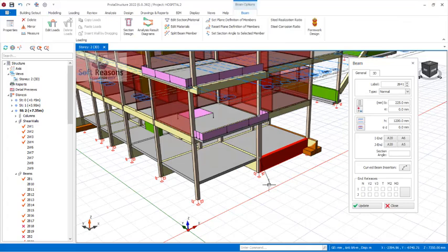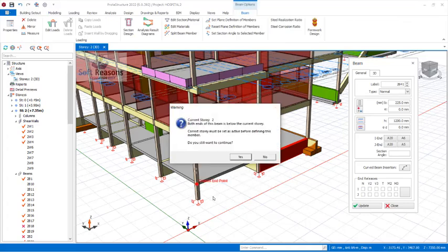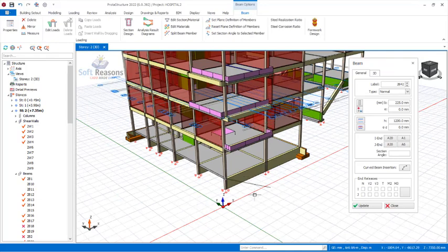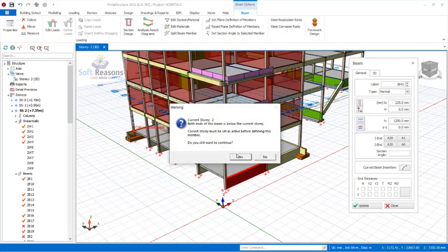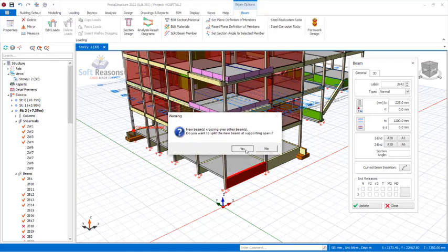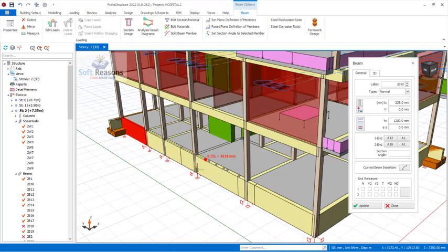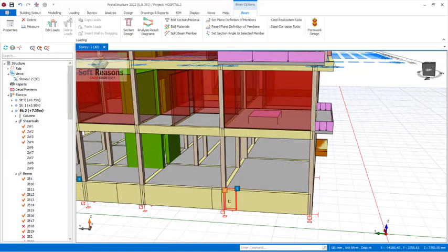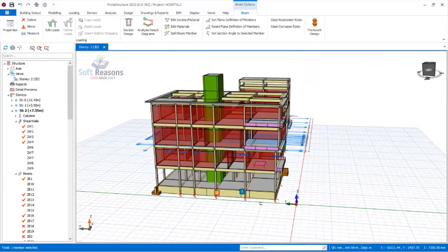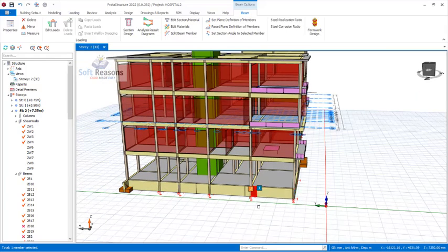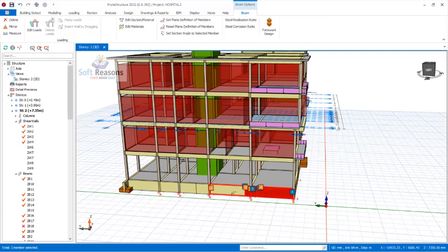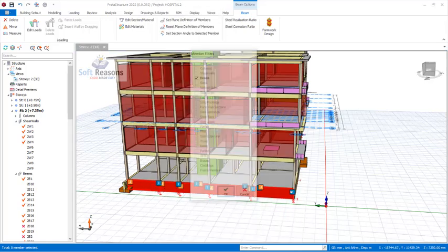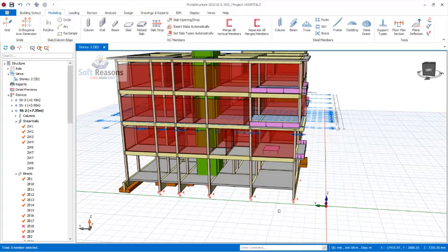So you have that all the way to this point. You can take all the way to this end columns, and then you can split this successfully. So that can be split, you can see. We have various splitting provisions right there, which I wouldn't like. You can see all of this is being split, which I wouldn't like. So you can get that selected by holding the control key, get rid of that, and then right click on delete to get rid of that beam, because it's not properly placed.